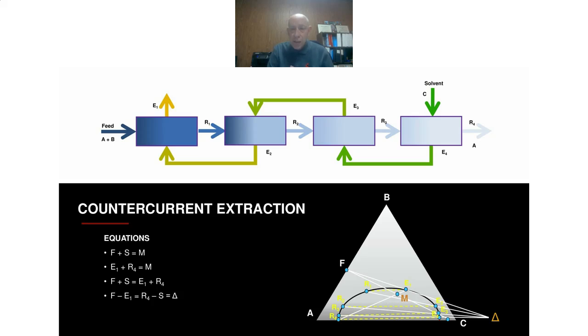Not exactly the same, obviously, but pretty close. But what you've done here is you significantly reduce the solvent usage. In this example, we're only using 25% as much solvent to do this extraction process. And that's where the economics of your process start to come into play, because that solvent typically has to be recovered downstream and recycled back to the extraction process.